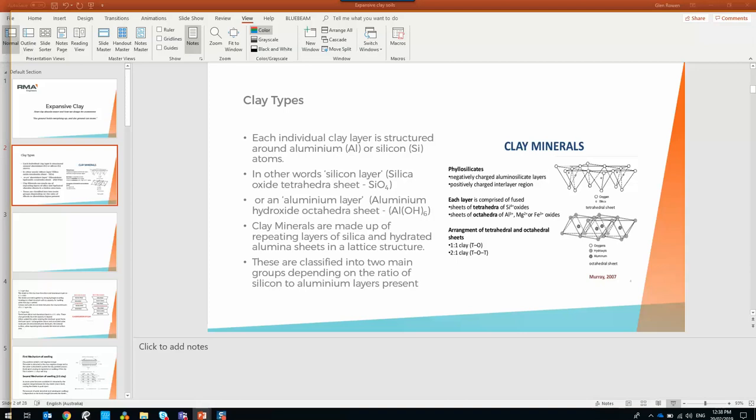So I've done a lot of work over the years, and I'm basically going to list you some footing schemes in order of effectiveness and how you can deal with building on these highly expansive clays. So all these systems rely on great drainage and other practices. Basically, the only reason these clays expand is if they're exposed to moisture. So if you picture them like a hibernating grizzly bear, it's sitting there and it won't harm you unless you put water on it, and then it will try and eat your face.